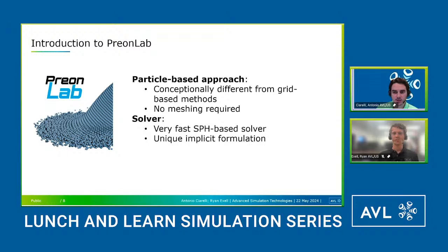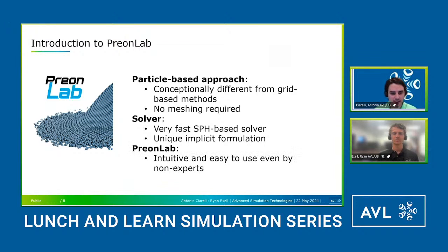So we're going to do a quick introduction and then we'll get into it. PreonLab is a SPH solver. So unlike your traditional CFD solving tools, it's not mesh-based. There's no need to spend hours to days meshing the area around it and the CAD itself. You use particle-based approaches to get a much faster simulation, both runtime and setup-wise. It has a very unique implicit formula instead of utilizing the traditional based. And as Thomas mentioned, it is very intuitive and easy to use, even if you're just picking it up from the beginning. It's definitely one of the tools easy to use and then takes a longer time to master.